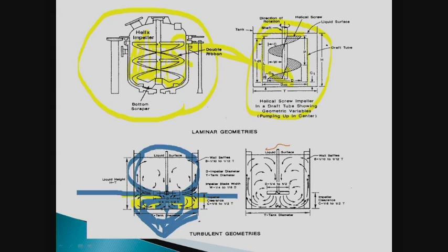If I go to this tank, obviously again, as it now sits, there's a dead zone here. The way you get rid of a dead zone is you put a feed through it. Good idea. But again, I don't have agitation when the liquid level drops below the agitator, so I always want to bring it down and have a small agitator on the tank bottom, and that actually sits in the dead zone. Further on down, I may have a cone bottom down here, and I need a tickler impeller to go all the way down into the bottom of that tank, and away I go.